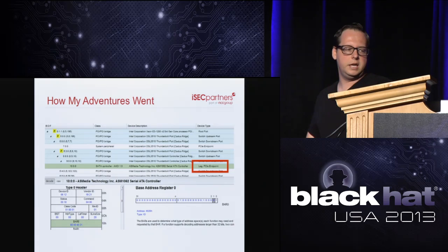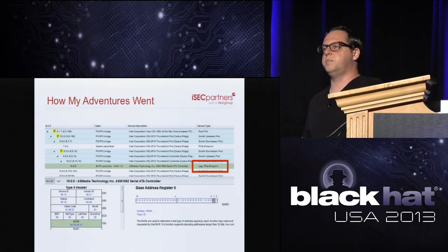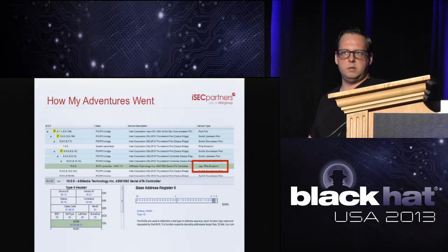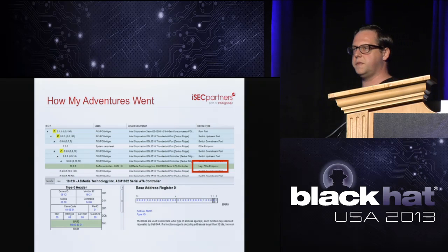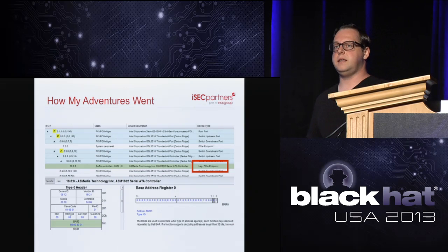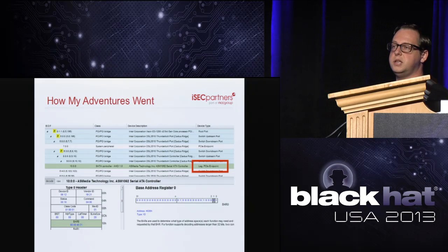So that was a pretty in-depth look at the hard drive. We've got a lot of information out. We got some great ways to pull some flashes and ROMs. We got some great ways to see what's going on. We know that the ARM Cortex is orchestrating the whole thing for Thunderbolt, and the Cortex is required. So maybe we can, and we have a pretty detailed pinout of our DSL2210 chip. So we're able to take that and look at other DSL2210 chips.